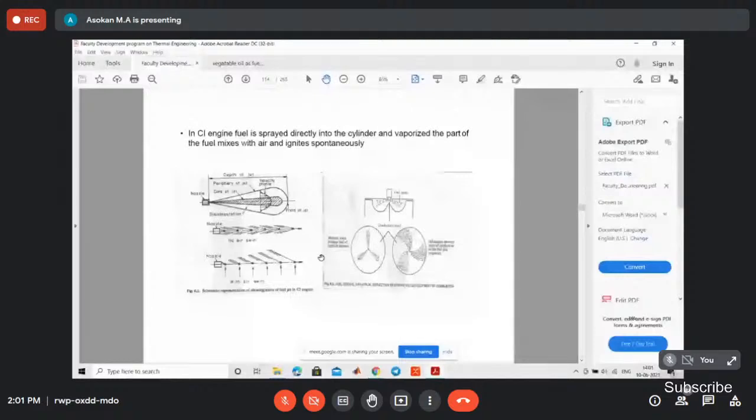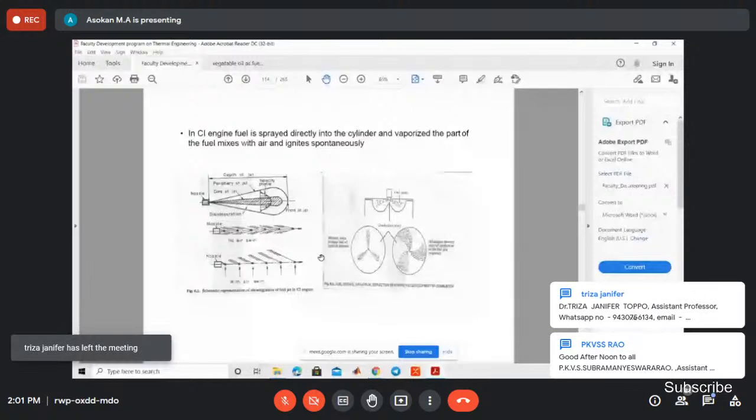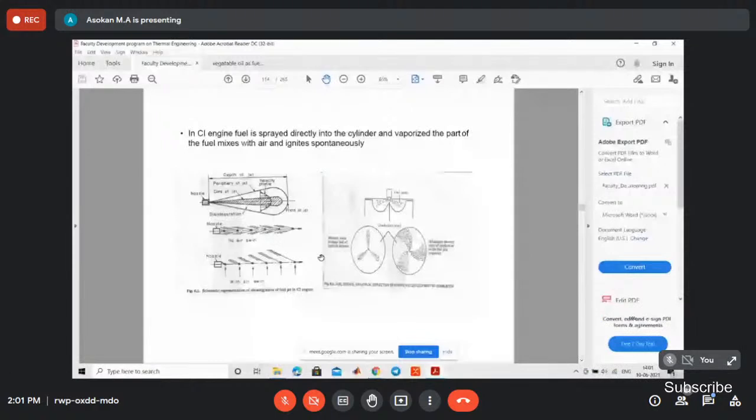So there is a failed combustion. So we can circulate the air in a swirling motion, so that the air carries the fuel droplets. Then the oxygenation takes place. Right? Then the fuel droplets are surrounded by the air, so that the heat transfer takes place. Then it attains the combustible range. So immediately ignition occurs at various locations. Right? That is the idea of the CI engine combustion.